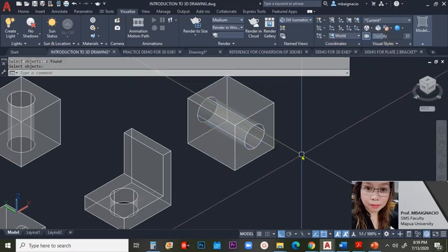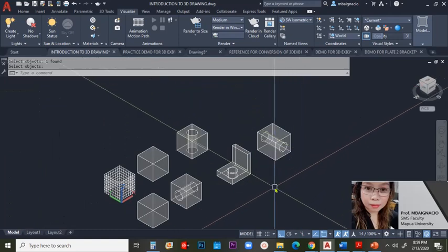So this is the basic editing tool, which is usually the basic tool that we use in editing our objects. Now, by the way, you can actually make use of fillet also as needed, but for the meantime, the commands extrude, subtract, and 3D rotate, including move if you want to move it from one endpoint to another, but be sure to attach it at a specific end-to-end point. So please be guided.